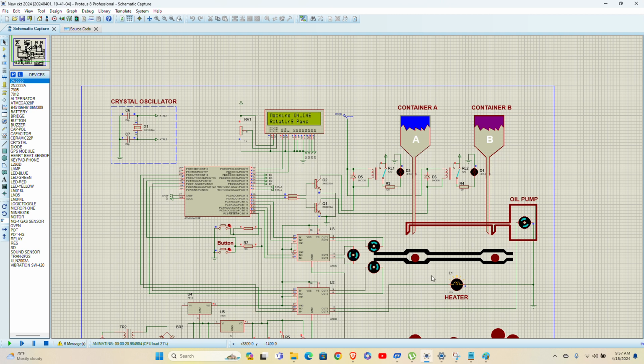So after closing the top panel, what will follow? It will flip this panel. After closing, you can see it will flip this, rotating the pans. So it will rotate these pans upside down. This will go up, this will go down. At this moment, the heater is off, the pump is off, and the paste is not filling.